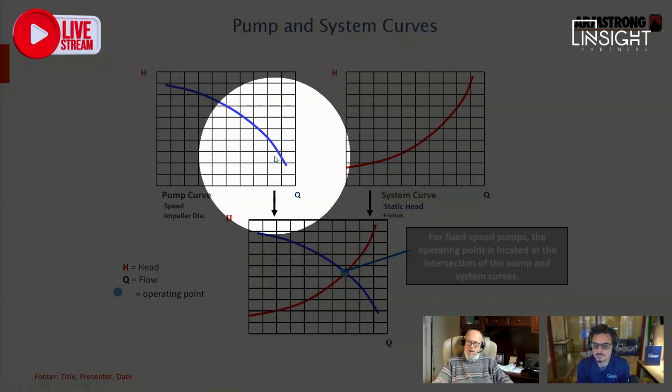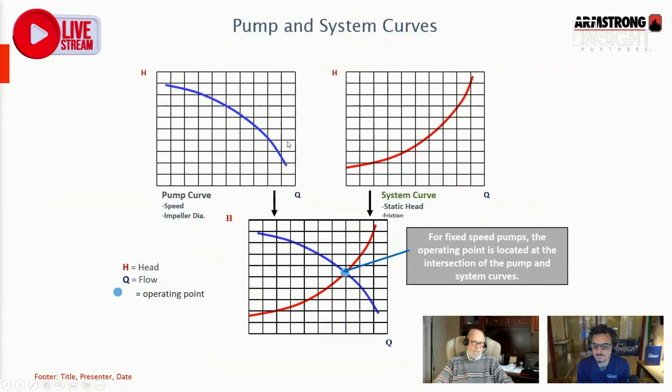Once you get out in this last 10, 15% of the pump curve, you really don't want to run there. You start to get into the unstable region of the curve, and yes, we show it out that far, but you really don't want to be running out in that range because the pump's just spinning so fast because of lack of pressure. The pump is trying to move a whole bunch of water, and the velocities are real high, and it's no different than a fan curve. When you get to the end of the curve, strange things start to happen.